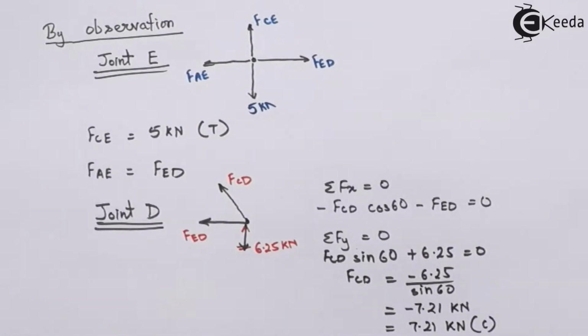I can see that the force in member CD is coming out as negative, so it is a compressive force.